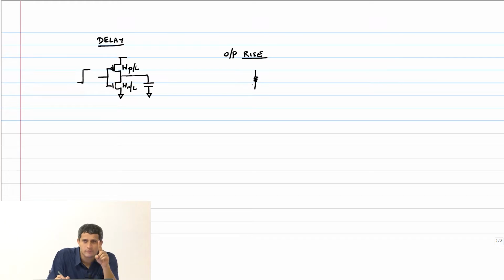And you remember that we calculated a resistance for the NMOS transistor when you discharge the capacitor, right? So similarly the PMOS will have a resistance R equivalent of P. Okay, this is my output Y. What happens to the NMOS transistor when you are rising? It will be off.